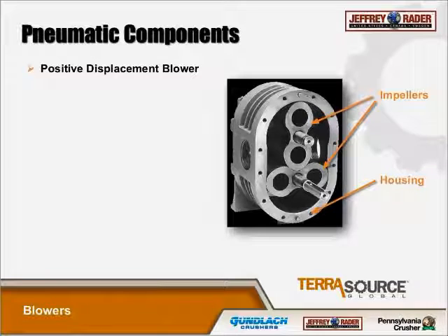We'll also include controls to monitor the conveying pressure. If the conveying pressure gets too high, the infeed will stop, but the blower continues to clear the line out from the material. If it stays high, then the blower will also stop because the line is most likely clogged and has to be manually inspected. We also include a built-in check valve in the discharge air piping that automatically closes when the blower stops, and that prevents back pressure from carrying material into the blower.